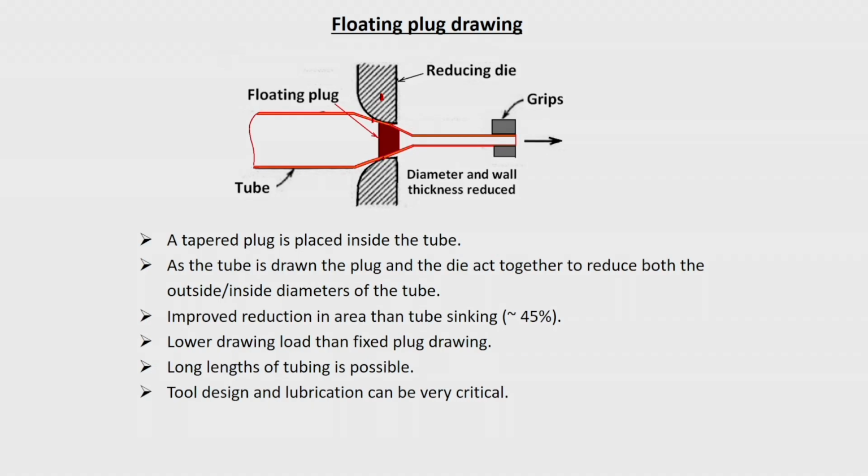And here the biggest advantage is that there is no restriction on the length of the tube which can be drawn. The limitation of the length depends only upon the maximum size of the starting tube material. So, you do not have any limitation on that. It can just come out and you have the tubes.